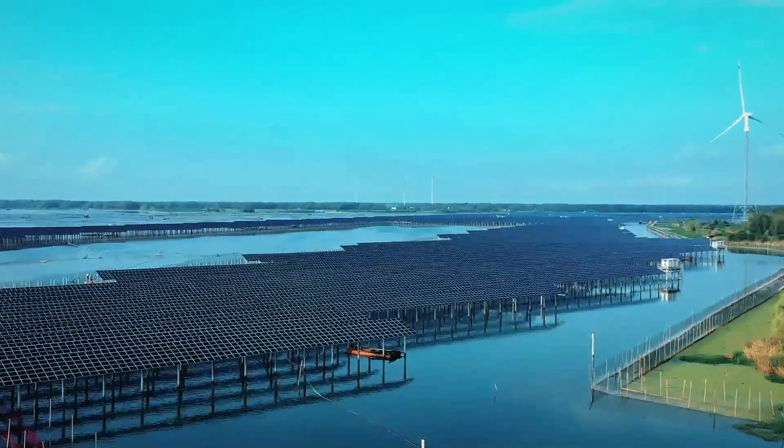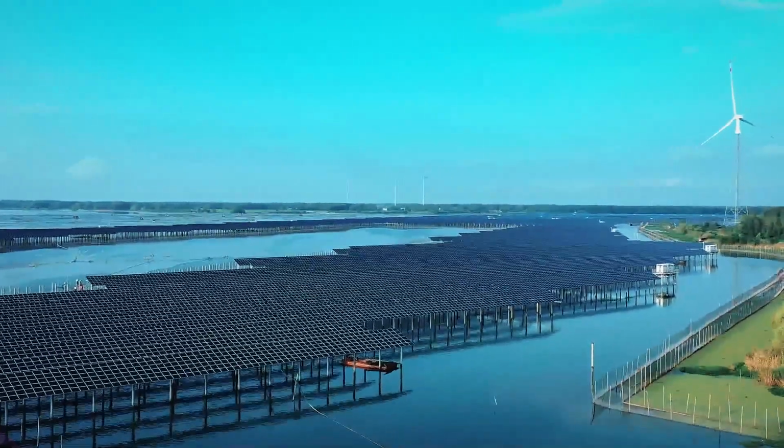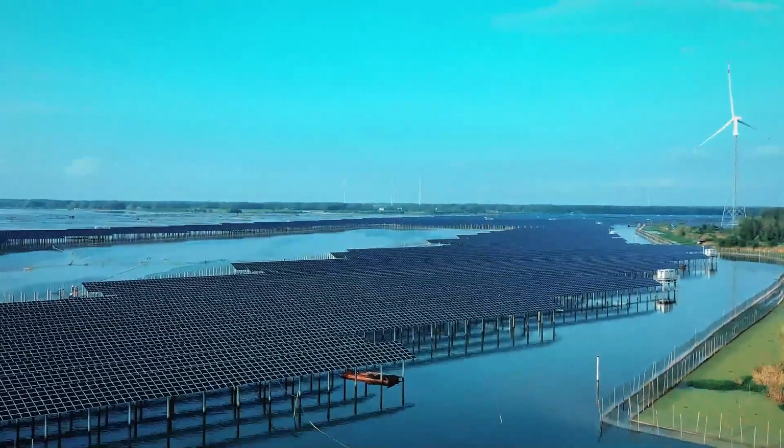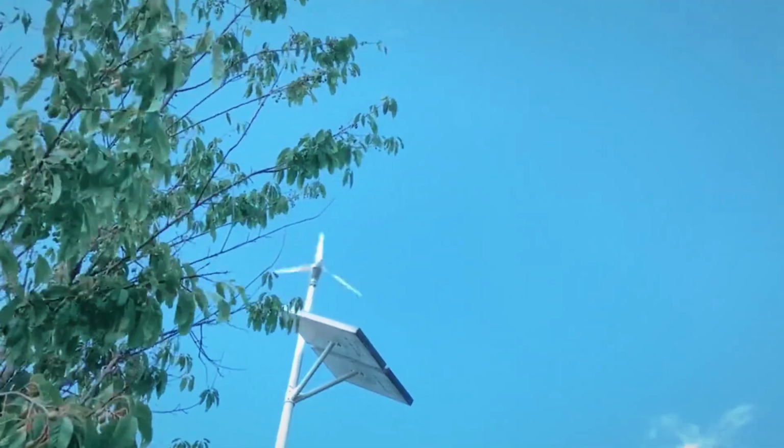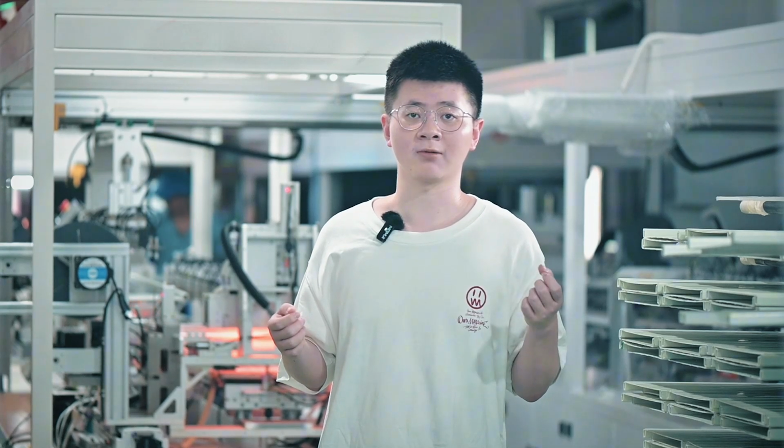Can I mix series and parallel solar panels? Yes. It is possible and common to mix series and parallel solar panels in a solar panel array. By combining the two wiring configurations, it is possible to create a solar panel array that meets the voltage and current requirements of your specific application. For example, multiple series strings can be connected in parallel if a higher current is required, while multiple parallel strings can be connected in series if a higher voltage is required.